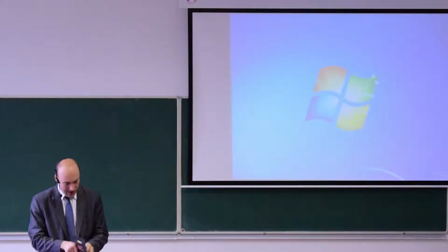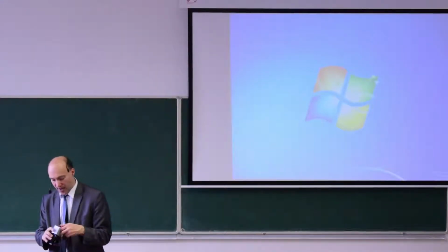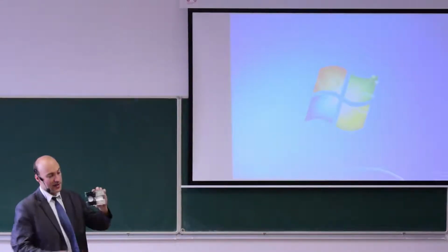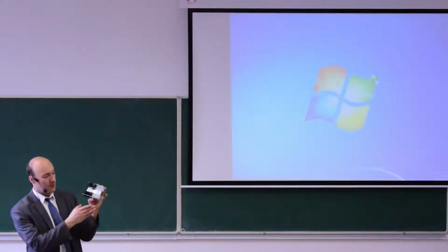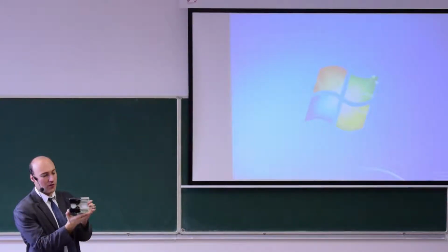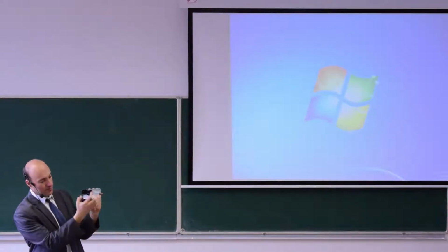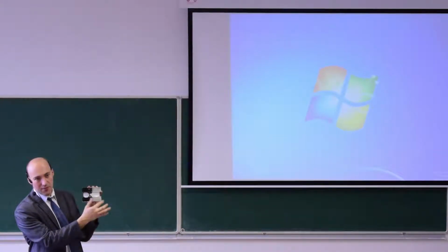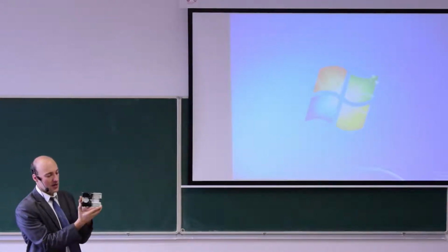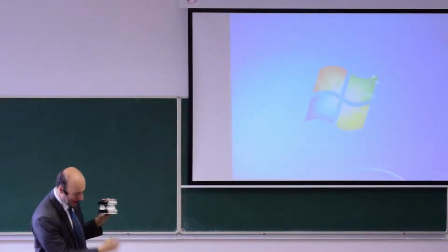A second option is that you use a special paint that you apply on the surface and that has a defined emissivity. So for example, if I want to measure the temperature on this heat sink, as you will do in the lab class, something from next week, the temperature should be the same around all the heat sink because it has a good heat conductivity, so there is no reason why one half should be warmer than the other one.